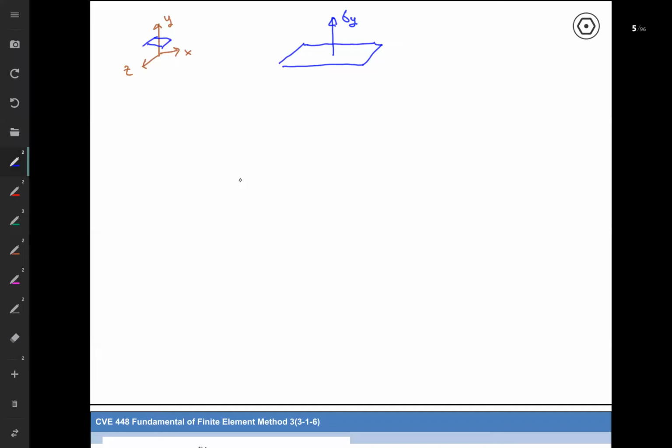Normal stress is the force per unit area, where that force is perpendicular to the area. So we should have another component. What does this represent? It should be tau what? What plane do we consider? Now we consider the y plane. It should be tau y, right? But its direction is along the x direction, so we call it tau yx.